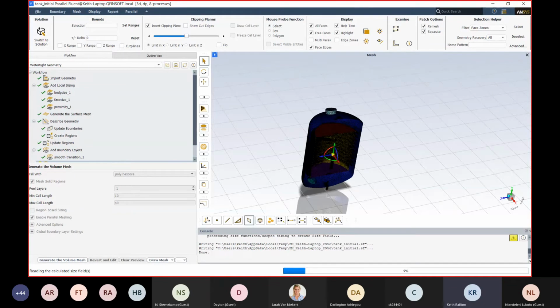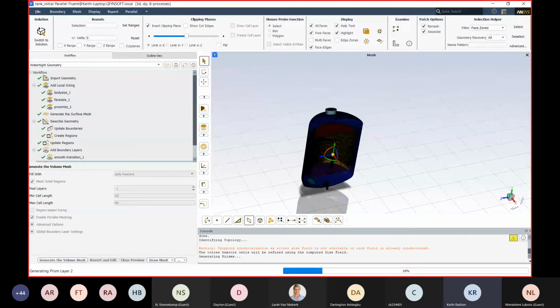So it needs to remesh the surfaces that are in contact where there will be shared topology. So again, it doesn't really matter too much, but it's easier through SpaceClaim. But if you are struggling, then you're more than welcome to do it in Mesher. And for example, if you were to import geometry directly out of some other CAD package, then obviously you would want to do your shared topology in the Mesher itself.